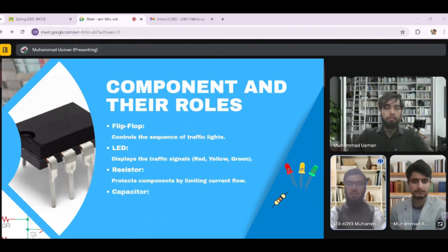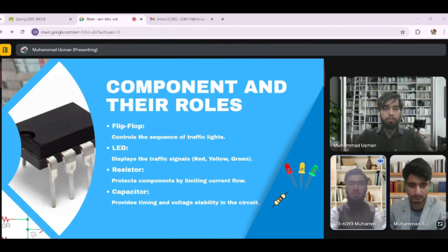At the heart of our circuit are two 555 timer integrated circuits, which are popular and reliable components for generating precise time delays and pulse signals. In our project, both timers are configured in astable mode, meaning they continuously produce square wave signals without any external triggering. These continuous pulses are essential for controlling the LED light transition.